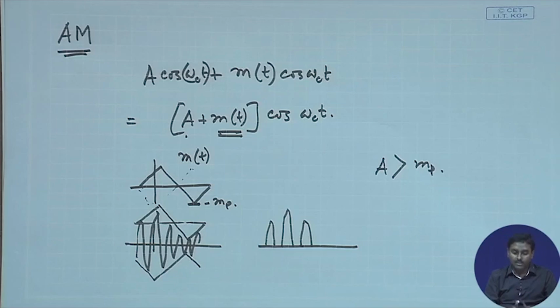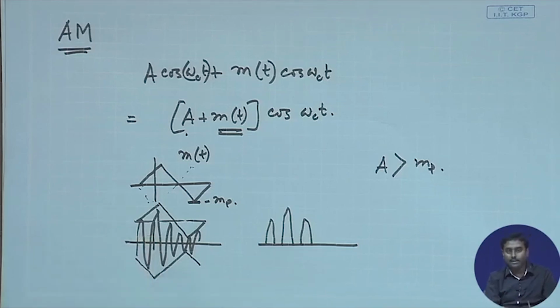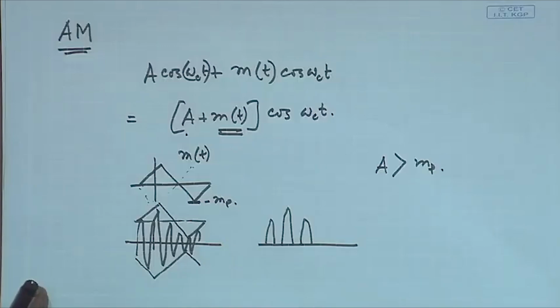This almost means this signal multiplied by a pulse train, which is exactly synchronized with this cosinusoid, isn't it? Because in the negative half, if I have 0 and multiply, it will become 0, and in the positive half, if I keep 1, it will just represent that signal.